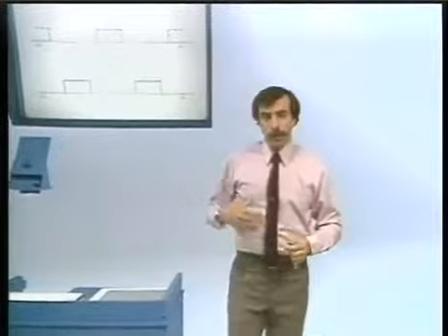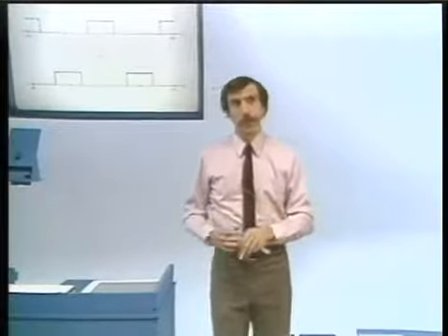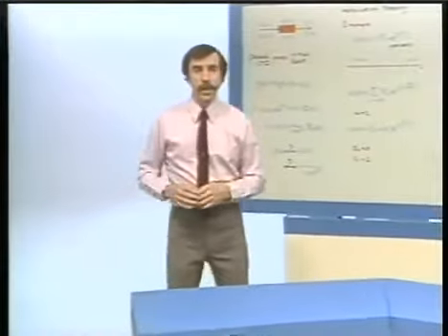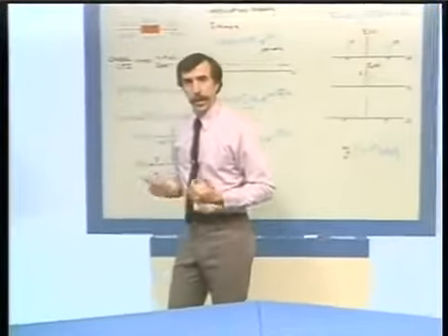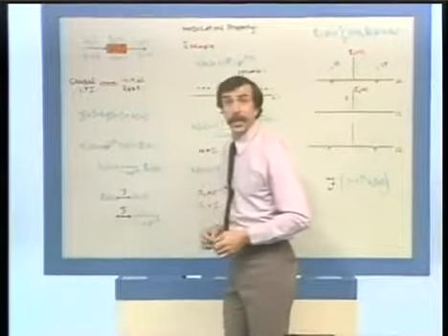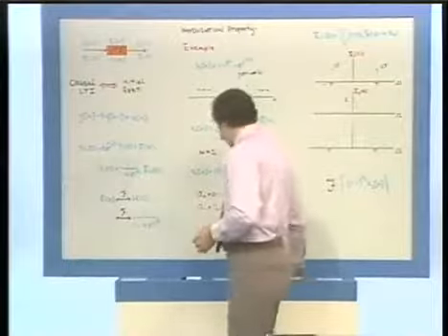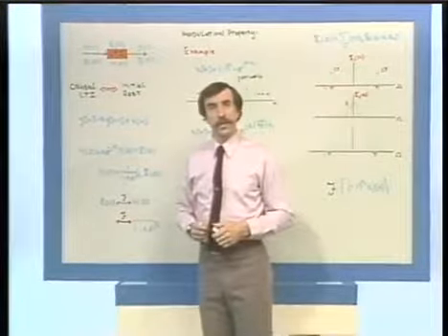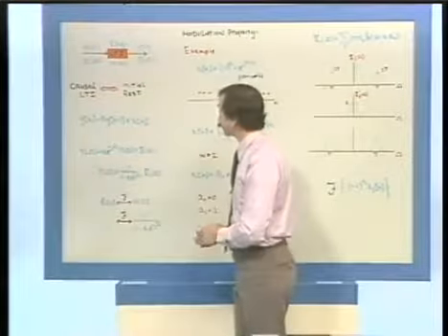Okay, so we've seen the convolution property and its interpretation in terms of filtering. More broadly, the convolution property, in combination with a number of the other properties that I introduced, in particular the time shifting and linearity properties, allows us to analyze systems that are described by linear constant coefficient difference equations. And this, again, parallels very strongly the discussion that we carried out in the continuous time case.